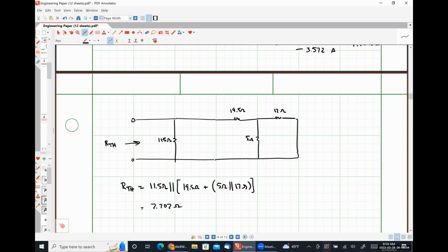If you are finding the Thevenin equivalent circuit or Norton equivalent circuit with respect to a set of terminals, don't take any elements out of the circuit. Just use those terminals that you're provided to do all of your analysis. So I believe in the in-class assignment, I give you one problem finding it with respect to a particular element and another problem finding it with respect to a set of terminals. So have at it. If you have any questions,